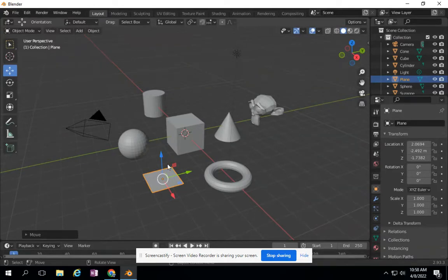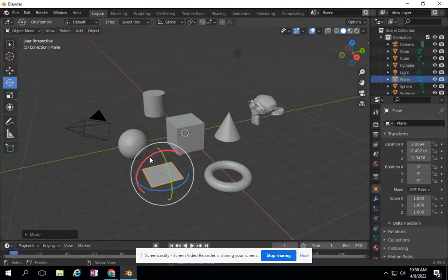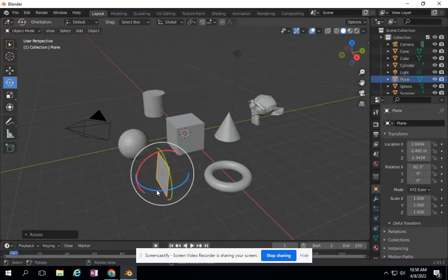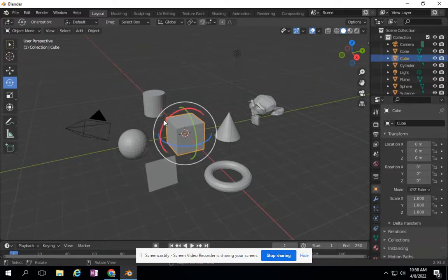So we already learned how to move a little bit, but I want you to point out that there's two other gizmos over here as well. So there's the move tool, but underneath that there's a rotate tool. And if I click on that, it allows me to take an object and rotate it along the axes as well. So I can start positioning these things using my rotate tool. So I get these little handles that allow me to rotate.